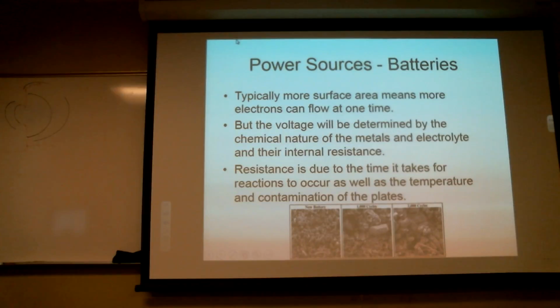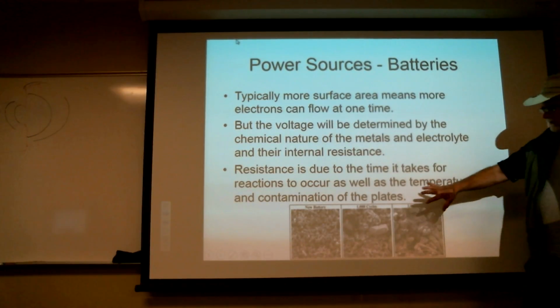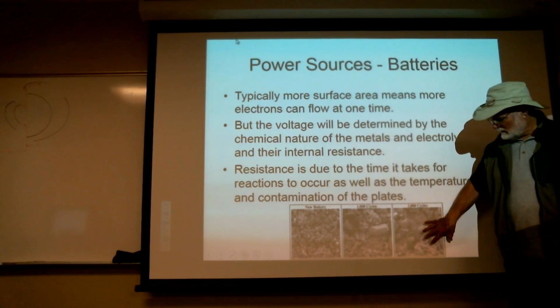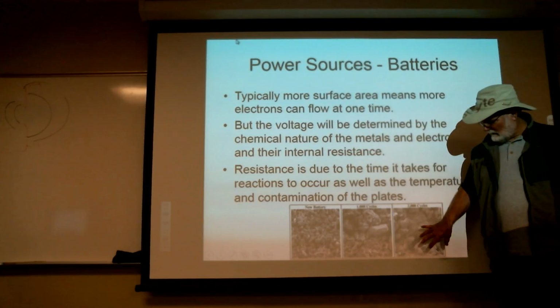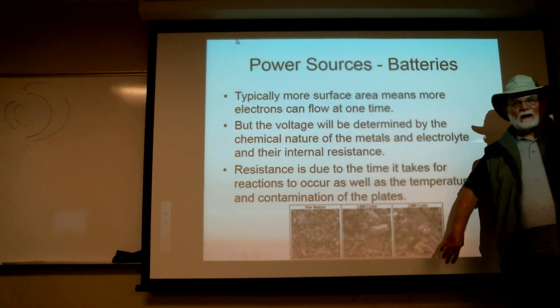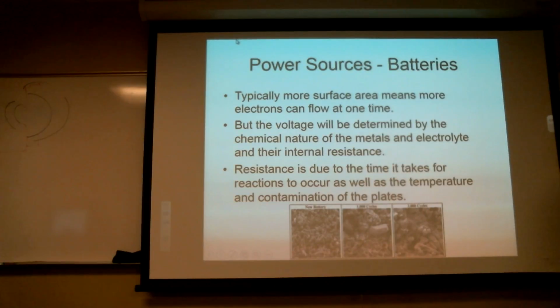As it discharges, you can see it start to change shape and state. Eventually, if it gets really crystalline, parts break off, and the parts that break off are no longer in the electrical circuit, so they don't reform. Now, there are some ways to rejuvenate lead acid batteries a little bit, but one of them is you pulse them with a high shot of current rapidly.